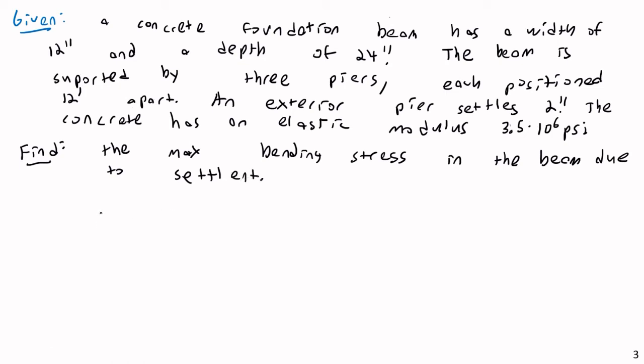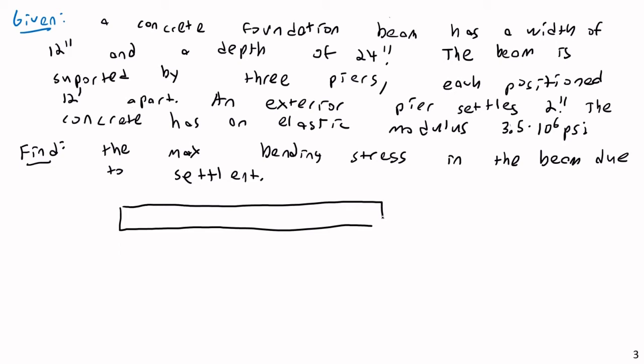So what's happening here is I have my great big foundation pier, or sorry, I keep saying pier, I should say beam, my big foundation beam here. And this is 24 inches deep. Now, truth be told, this is a very deep foundation beam, although you never quite know sometimes. So this is a 24-inch deep beam, and underneath this are 3 foundation piers, which could be drilled piers or whatever they might be, and they would go down a certain distance.